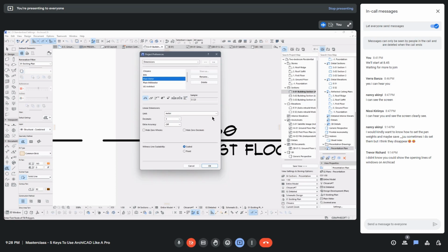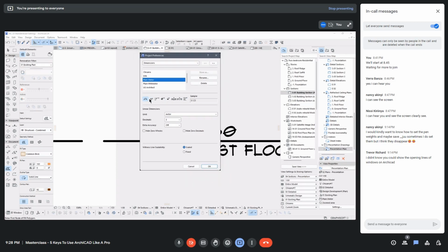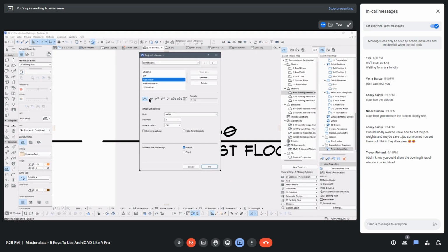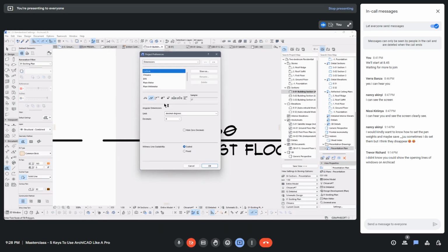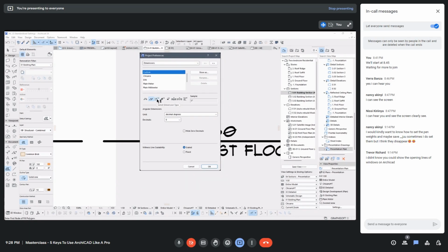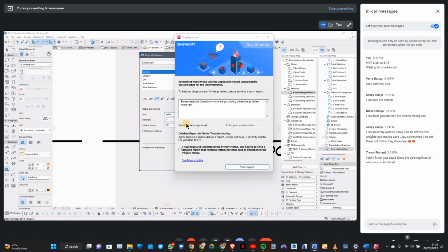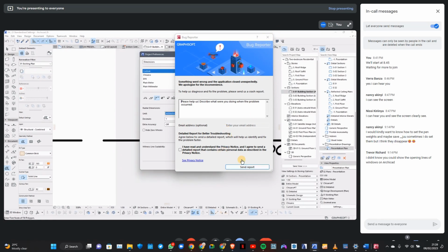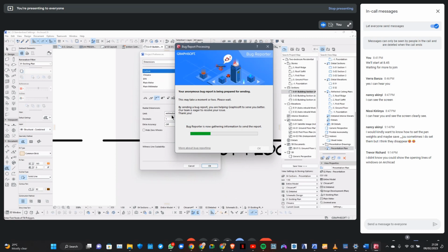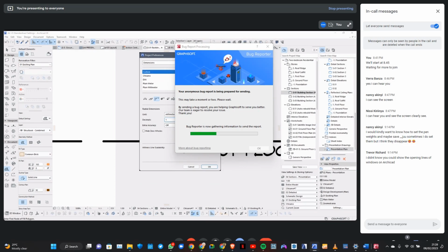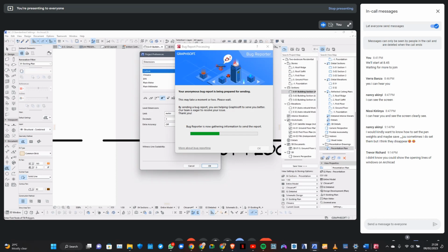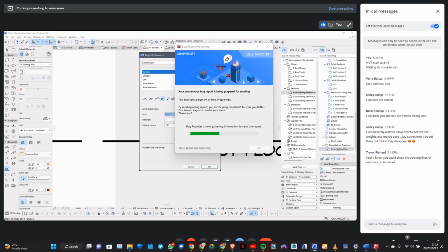So what I do is I start here under dimensions. If it's a dimension type, how do I want it to show? I want it to show as a millimeter. Decimals, no decimal. Next one, if it's an angular dimension, decimal degrees. Radial dimension, same thing, millimeter. Decimal degrees off. Yeah, that one, millimeter, same thing, decimal degrees off.